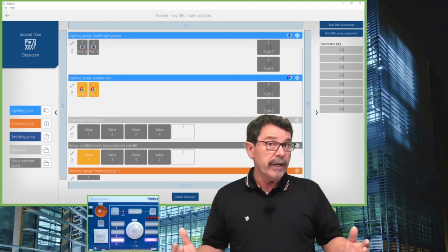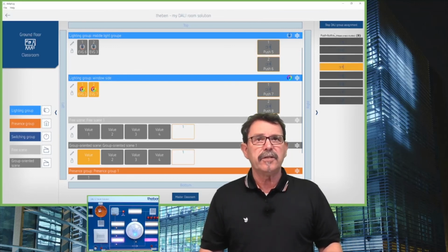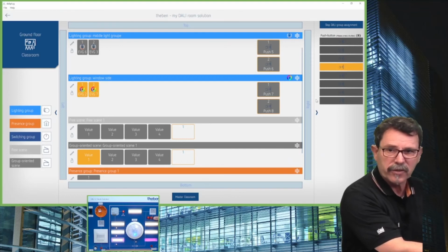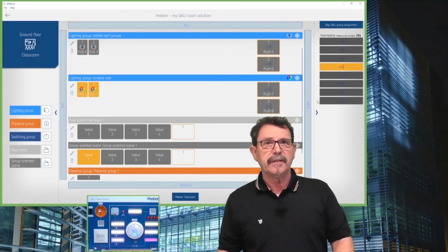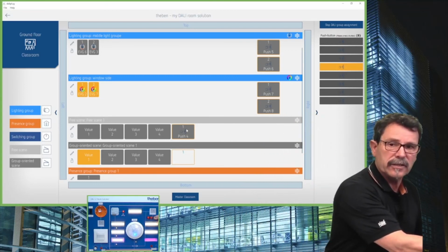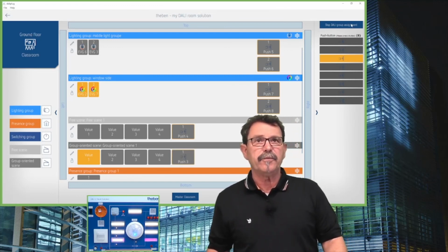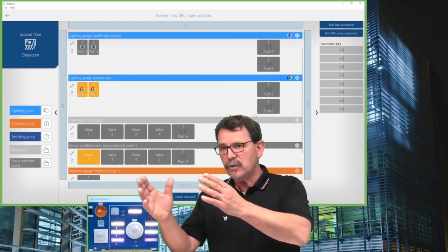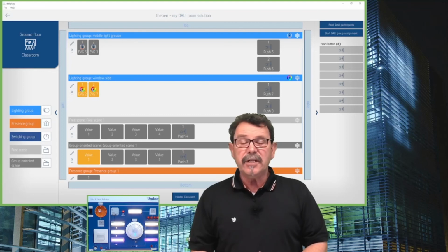So, okay, like mentioned, now we need a push button to call these scenes reasonably up. For that purpose, again, we start this DALI assignment, and for this purpose I use here these two push buttons. I think you can see down there in the presentation. So I click on that push button, and this one I link to here. I press on the next free available push button, which is this one, and I finish the group assignment. And then the reasonable push buttons are linked to the reasonable groups finally to call them up.